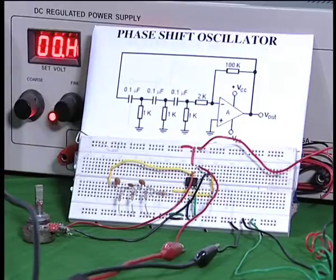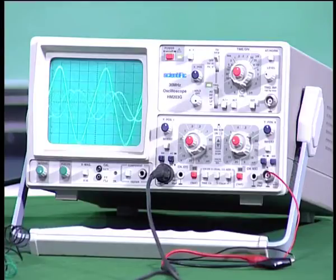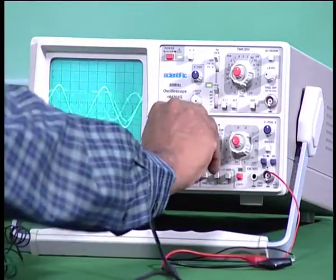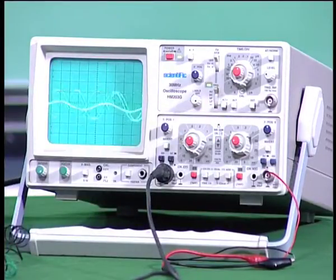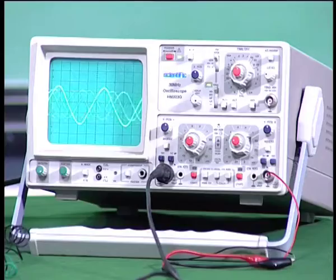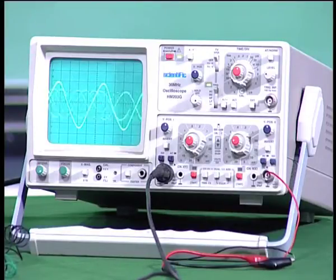Now, how do you know the output waveform that I get is due to the oscillator? Now, I am varying the gain factor here. You can see that when I get very high amplitude, and when I change that, now I do not get any oscillation. Now, when I change it to the right gain, about 29 or so, you see on the oscilloscope the building up of the sine wave. Now, the sine wave builds up, it goes up to that, and if I now reduce, it goes to 0. Therefore, it is only the